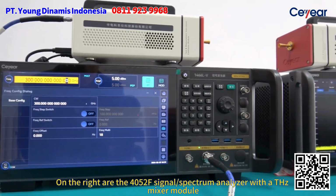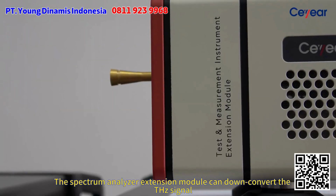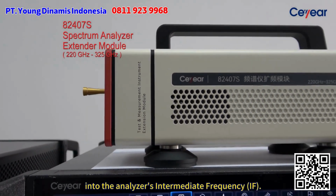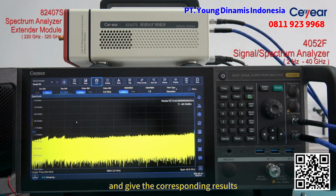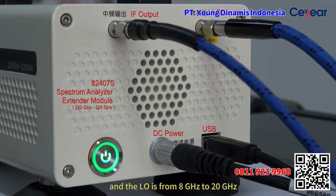On the right are the 4052F Signal Spectrum Analyzer with a THz mixer module. The Spectrum Analyzer extension module can down-convert the THz signal into the analyzer's intermediate frequency. The analyzer will further process the RF signal and give the corresponding results. Here, the RF is 425 MHz, and the LO is from 8 GHz to 20 GHz.